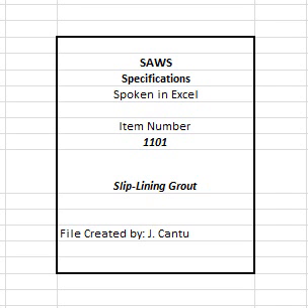B. Pressure gauges. 1. Pressure gauges shall be equipped with diaphragm seals, have a working range between 1.5 to 2.0 times the design grout pressure, and have an accuracy within 0.5% of full range. 2. Provide one pressure gauge at the point of injection and one pressure gauge at the grout pump. 3. Grouting shall not proceed without appropriate gauges in place and in working order. 4. Grout pressure gauge and recorder shall be installed immediately adjacent to each injection port.